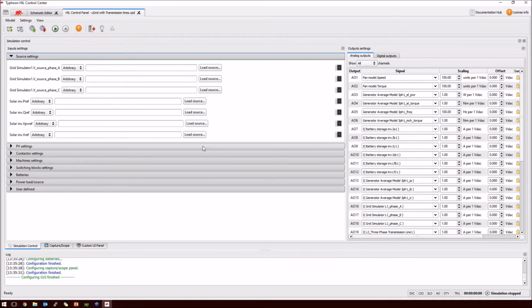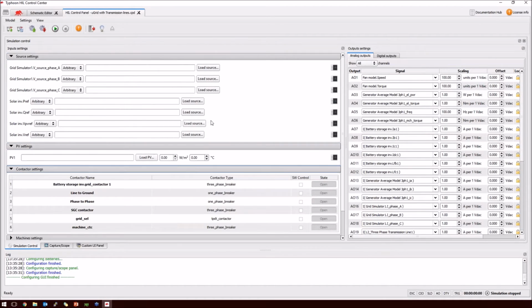And you'll see here on the left, we have the placeholder for defining all of your sources. And on the right, we have all of our mapping to hardware. So those current meters we were looking at earlier, we'll actually take these and map them here, with scaling and an offset if it's needed, and that will map it to that actual channel.